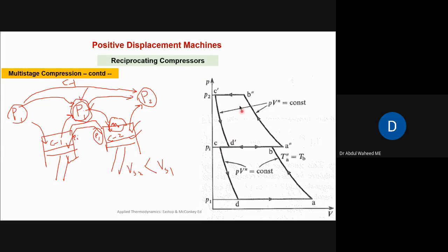जब ये single stage compressor था, so then we had the same fixed swept volume for very high pressure ratio. That's why volumetric efficiency dropped. So in this way, we can increase the volumetric efficiency by using two compressors instead of one. We can also go for 3-stage or 4-stage compressors depending upon कि ये जो ratio है कितनी ज़्यादा है.